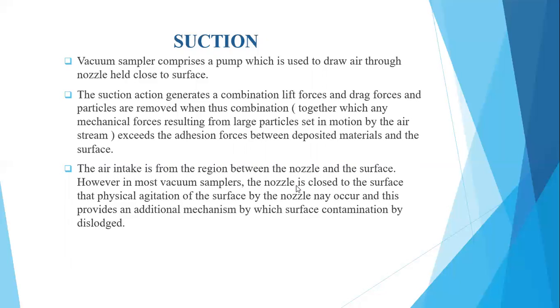The suction action generates a combination of lift forces and drag forces, and the particles are removed through the combination, together with any mechanical forces, resulting in a large particle set in motion by the air stream that exceeds the adhesion forces between the deposited particles and the surface.